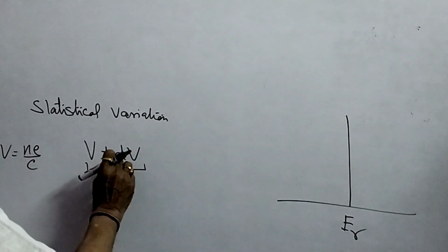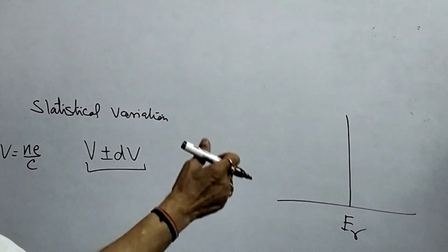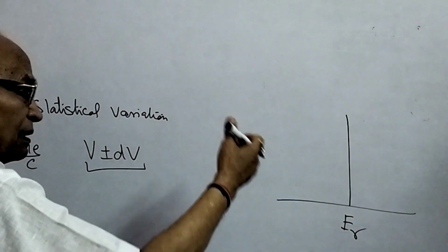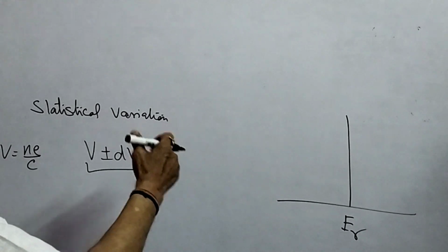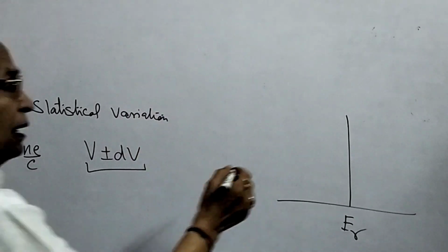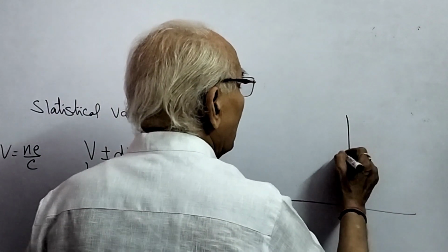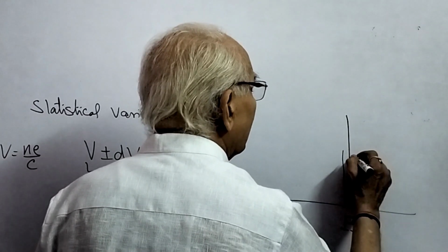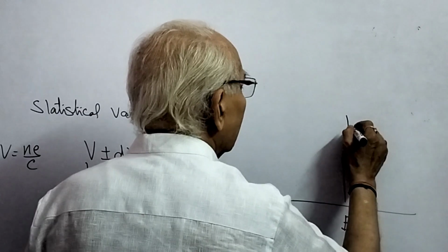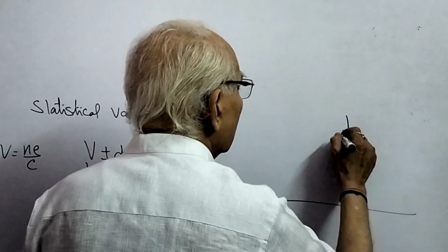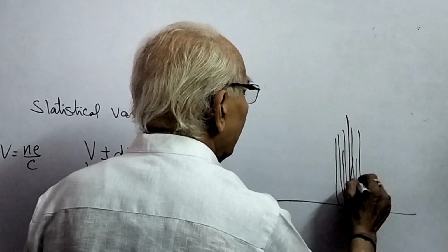No, but by statistical variations of various factors at multiplication, at optical transfer, at the diode multiplication, etc., we get this variation in the pulse height. Pulse height may vary like this, for a small variation.